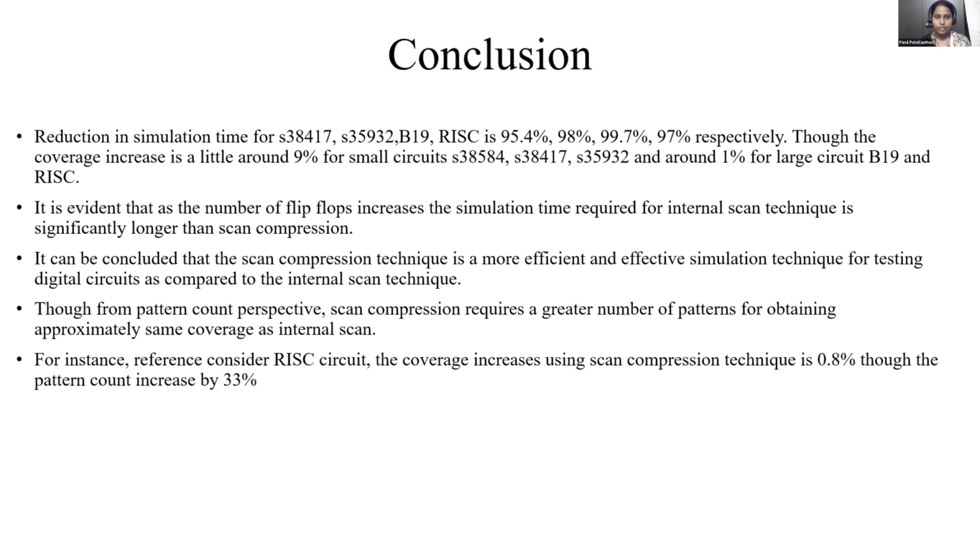And the second thing that you have observed is that the number of flip-flops in a scan chain, even for internal scan, is less than the number of flip-flops that I have shown in a design. The reason behind that is the tool internally does certain optimization. You have the power to ask the tool not to optimize, but I just let the tool optimize. So when it optimizes, it sees certain flip-flops as memory flops.